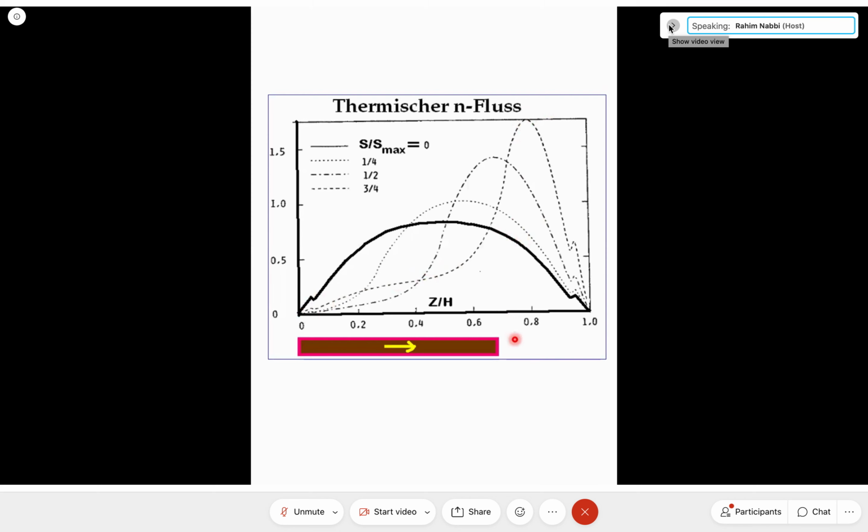At the end of a cycle, the big part of the control rods are staying at the upper part of the reactor core, and you see here the solid line, and the reactor neutron flux or power distribution gets a symmetrical shape because there is practically no effect of absorption by control rods, as they have been practically removed from the reactor core.